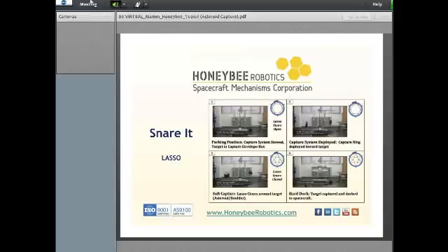And then in block 3 you can see in the graphical representation in the upper right corner of each block is the configuration of the snare. So this is a spring energized snare that's driven by a winch. And so once the capture ring is in place and the snare surrounds the target, then the winch closes and constricts from a dilated state to a constricted state around the target.